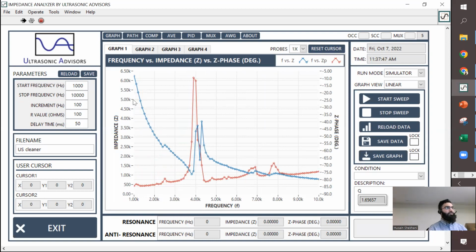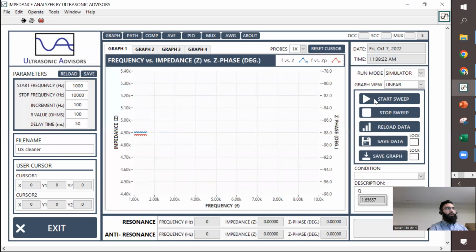As you can see, the blue is the impedance. You see a resonant point happening here, and then you see the phase increasing, which we'd expect. Some people have an issue with the phase not reaching 90. They think they saw somewhere that the phase starts at -90, goes to 90, and comes back down. The phase does not get to -90 if the coupling factor is low and the quality factor is low. It will not get to positive 90 in the inductive part.